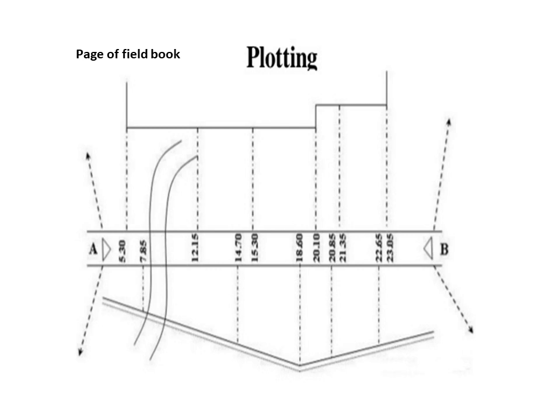They are called station points A and B, and on the left as well as on the right of line AB are the objects, and the dotted lines indicate the offsets, and these offsets make an angle of 90 degrees to the survey line AB. Therefore all these offsets are called perpendicular offsets.